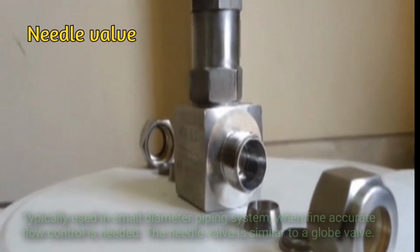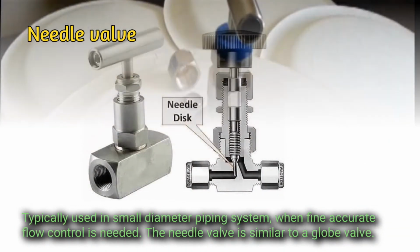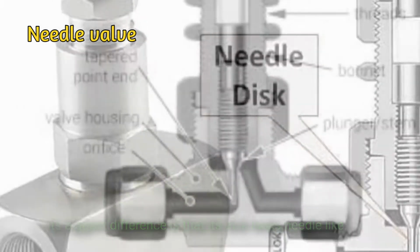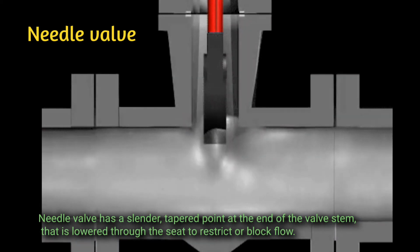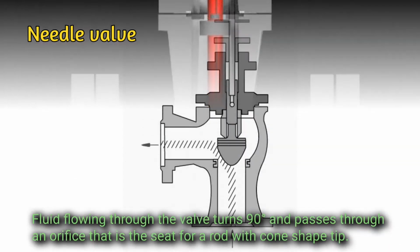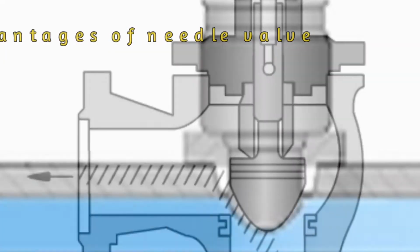Needle valve, typically used in small diameter piping system, when fine accurate flow control is needed. The needle valve is similar to a globe valve. Its biggest difference is that its disc looks needle-like. Needle valves have a slender, tapered point at the end of the valve stem, that is lowered through the seat, to restrict or block flow. Fluid flowing through the valve turns 90 degrees and passes through an orifice, that is the seat for a rod with cone-shaped tip. Advantages of needle valves.